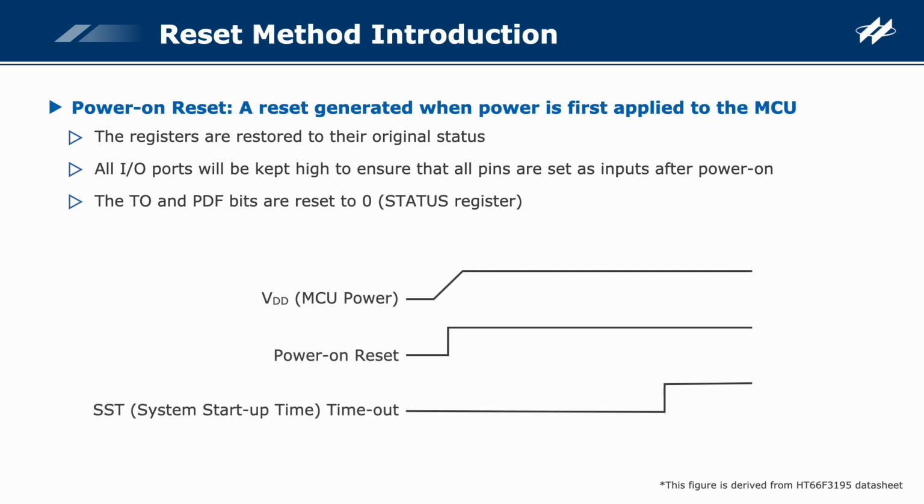Taking the HT66F3195 as an example. A reset occurs after the MCU is powered on. It begins to operate normally after about 16 milliseconds, during which time a series of reset actions are performed inside the MCU.